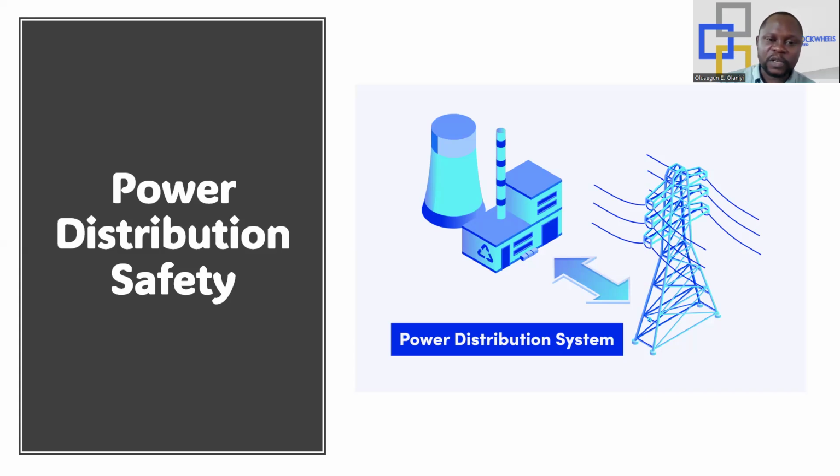Then we also need to protect our devices, and that is why it is important for us to do grounding. Among the components, we also have fuse, which is used to protect against overcurrent by melting or breaking the circuit. Grounding equipment is also important. It saves by directing electrical force to the ground and protects your devices or even people around them. We also have surge arresters. I visited an oil company recently and discovered that there are different types of arresters. This also protects against voltage surge caused by lightning or by switching off and on or changing over of operations. These are also things that we need to put into consideration.